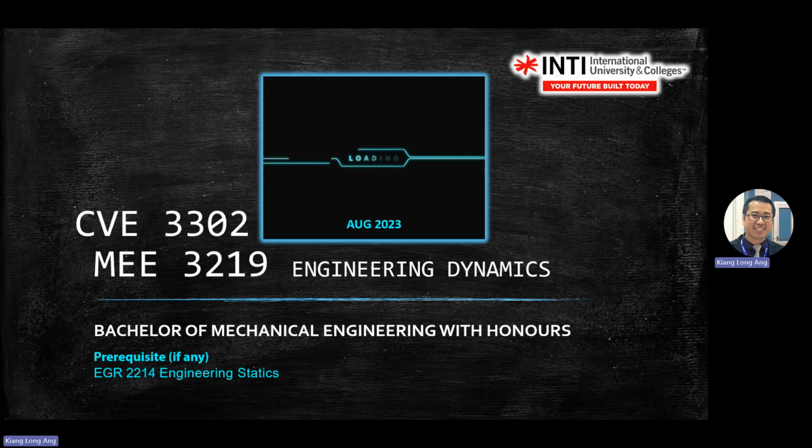If it is linear, you split into x and y: the sum of forces in x equals max, the sum of forces in y equals may. But if it is curvilinear, then you have normal and tangent directions: the sum of forces in normal equals man, the sum of forces in tangent equals mat.